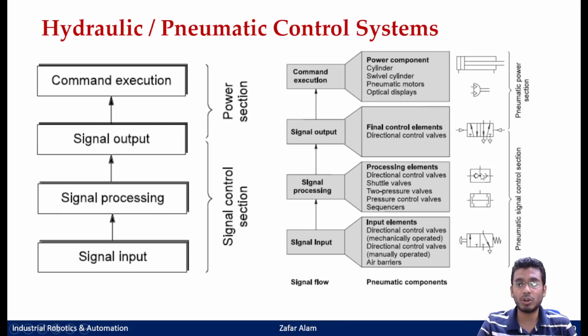So if you can see here, all your OR valves, your AND valves, that is the shuttle valves and your two pressure valves, are known as your signal processing valves. They say, based on the different input elements, how these input elements have to be processed before actuating my output. And what is my output here? My output is finally my valve. Which valve? It will be the valve that is finally going to operate my cylinder, be it a single acting cylinder or a double acting cylinder. So in case of a pneumatic circuit and a hydraulic circuit, these output elements will always be your pilot pressure.